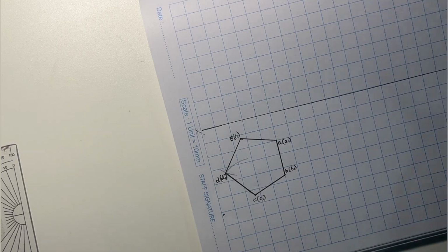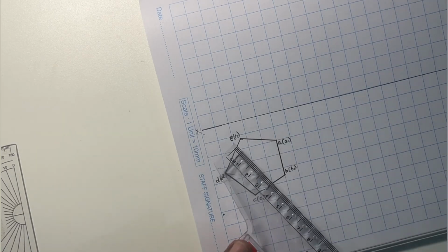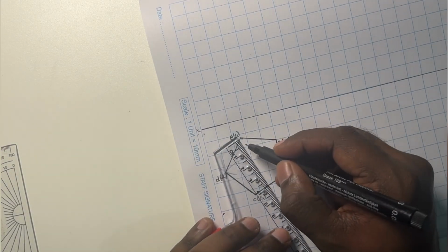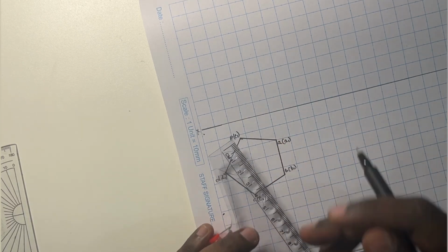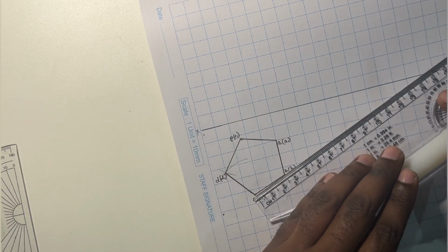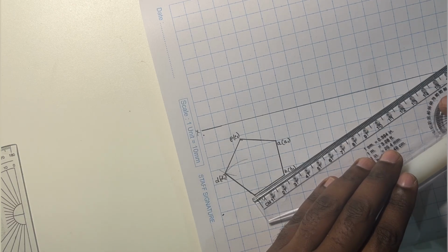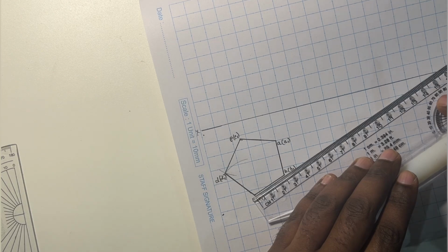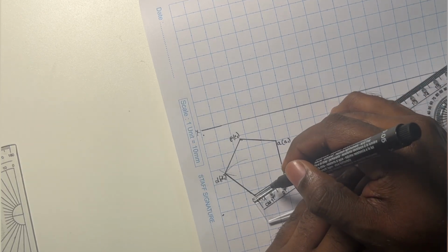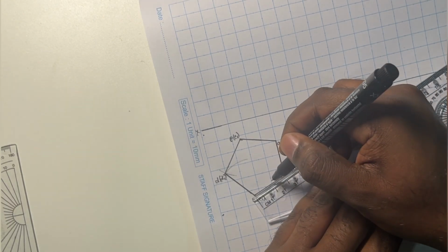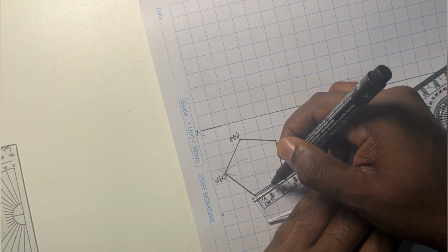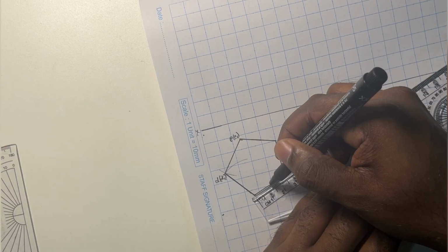And next I need to mark the axis. So to get the axis, I require the centroid of this particular prism where the axis is going to originate. So how do I mark this? I'll consider the corner point and the edge opposite to that corner point. So the edge is 2.5 centimeters. So I need to locate the midpoint of this 2.5 centimeter line. So it will be around 12.5 mm. So I cannot mark 12.5 mm. So somewhere between 12 to 13 mm, I'll be locating a point and mark the center point of this particular edge.